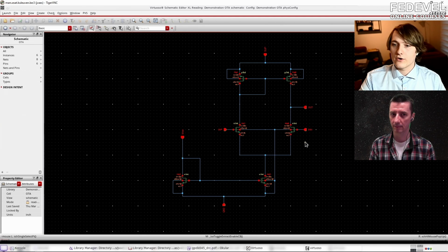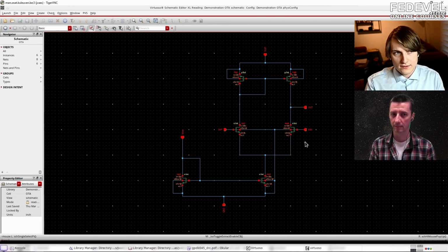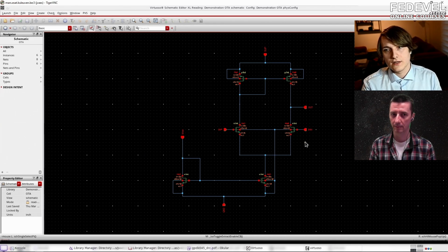In order to get more current capacity, we might make the transistor wider, because then it's like putting more of them in parallel. And so you get more gain as well, because the same gate voltage is now multiplied by a larger amount. And so that's really the art of analog IC design, is that we need to balance all of those factors and understand the limitations of those factors to design our cell.